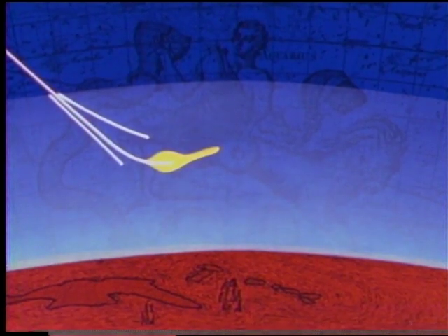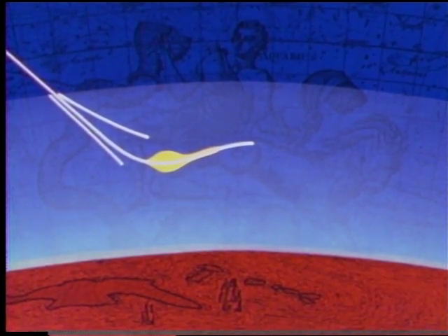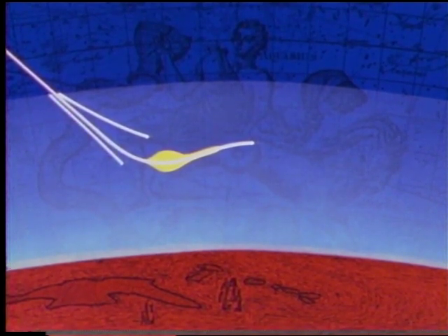It will enter on a given flight path and proceed downward to the pull-up point. Just before pull-up, it enters the atmosphere dense enough to allow aerodynamic control of its landing point and begins its first control period. The command module will then climb until it skips out of this denser atmosphere. The skip is primarily to increase the maximum range of the spacecraft and to reduce the aerodynamic heating load on the heat shield.